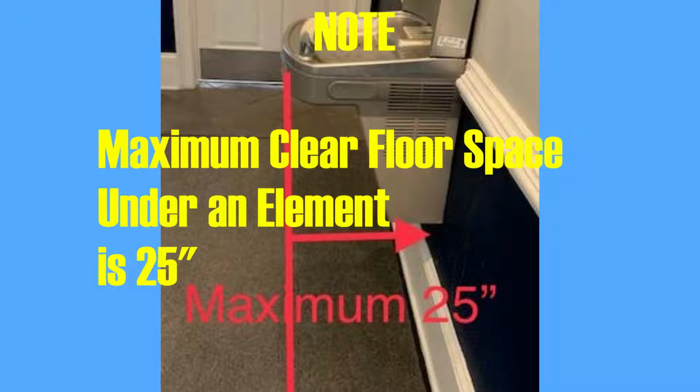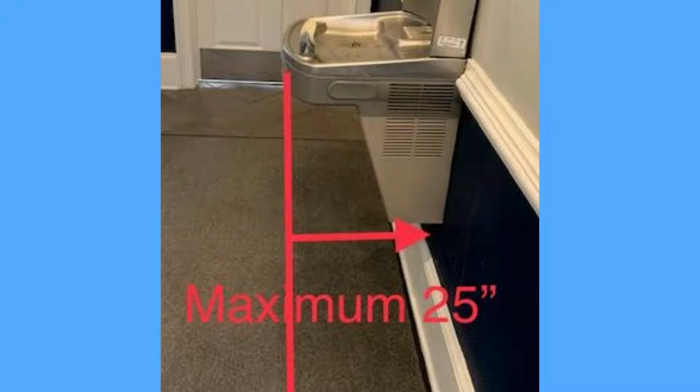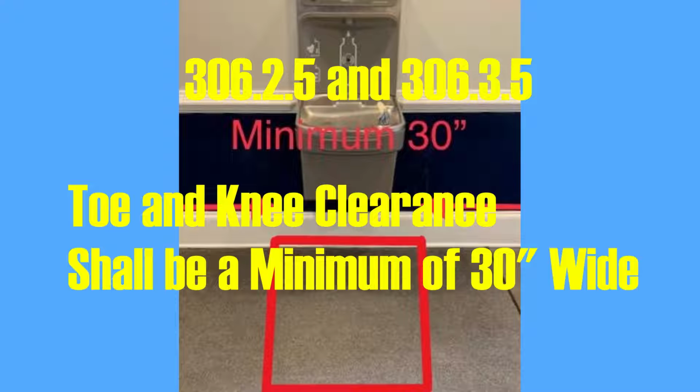Note that the maximum clear floor space under an element is 25 inches beyond the front edge of the element. Sections 306.2.5 and 306.3.5 state that toe and knee clearance shall be a minimum of 30 inches wide.